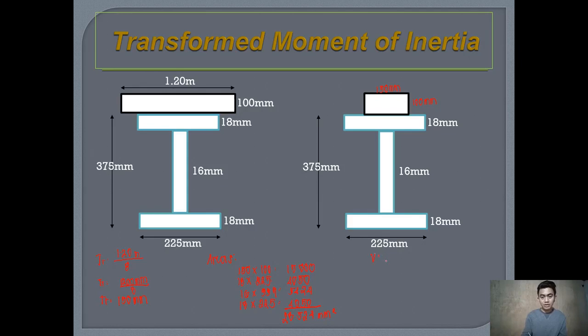So I will have here the total area, which is equal to 28,524, multiplied by the distance of the neutral axis to the top of our composite beam, equated to each of these areas. So I have here 15,000, and then the distance of the centroid of our steel section to the top, so multiply this one by 50, plus 4,050.